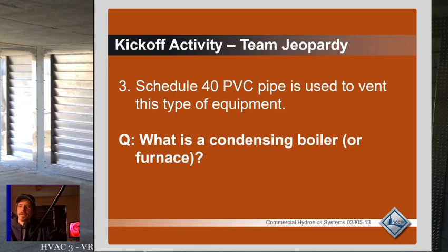It's not really the thing to be wary of when it comes to using PVC pipe for venting, and something you want to think hard about if that's what you like to do all the time, which is, most guys, especially when it comes to boilers. You want to try and keep that flue temperature as low as possible, or the water temperature in that case, because the higher the water temperature, the higher the flue temperatures are going to be.